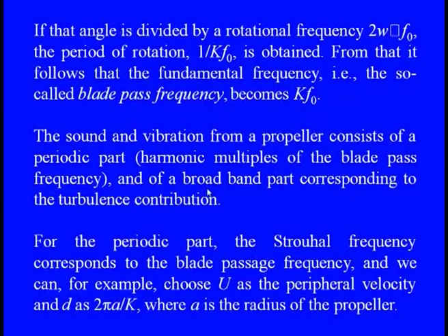And when you see the vibration of the sound which is coming out through the propeller, it consists of a periodic part, meaning there are various harmonic features, like multiple excitations according to the harmonics of blade passes frequency. And also we have the broadband, which shows the turbulence effect existing in this flow motion, and because of that a huge amount of amplitudes are created.